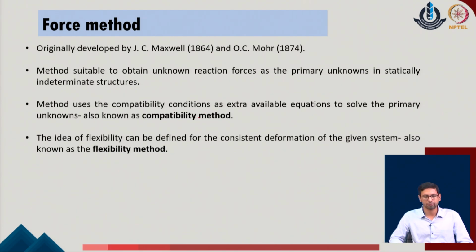So, the force method was originally developed by J.C. Maxwell and O.C. Mohr somewhere around the same time, but independently. The method is suitable for identifying the unknown forces of the given system. So, the primary unknowns which we consider for the force method are the reactions of the given system, and that is also one of the reasons for calling it a force method, because our primary unknown parameters become the forces for the given system.